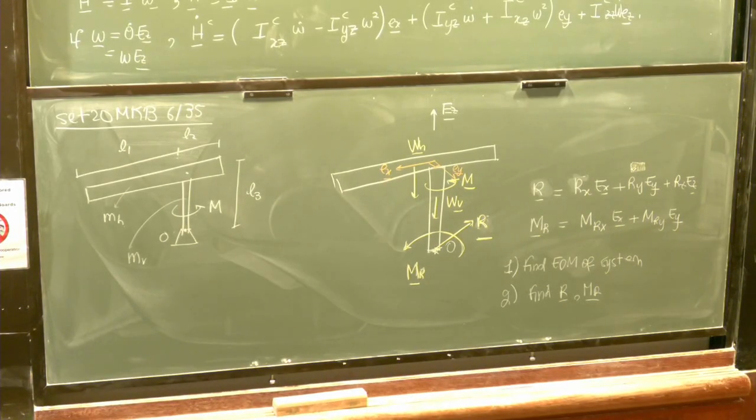What is it? Is M essentially like the... What do you think? Well, since it's a coupled moment, the 100 pound inches is a couple that's being applied on the bar. It's along EZ, right? The reaction moment is a reaction moment due to the support. So they're different, right? Even the direction is different. And the 100 pound inches along EZ, by the way, you need to convert this to pound feet. And the other one is along x and y. Okay?